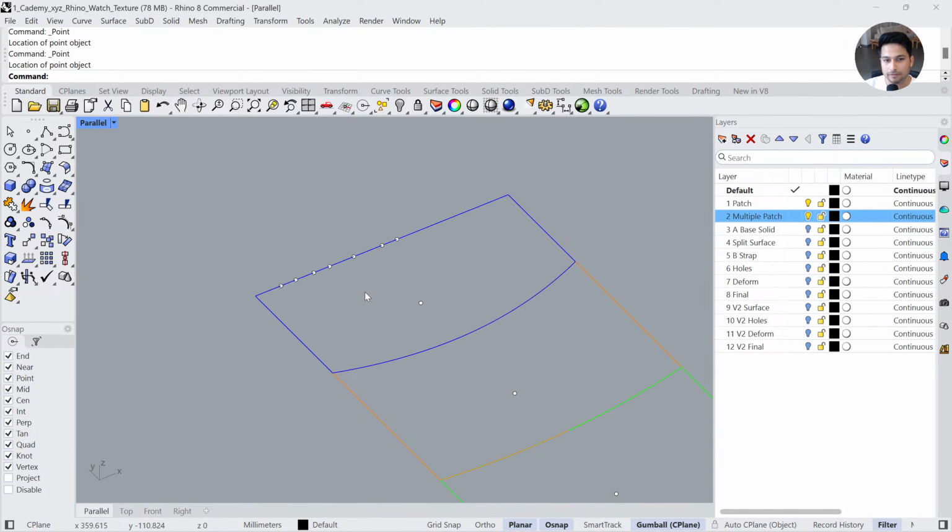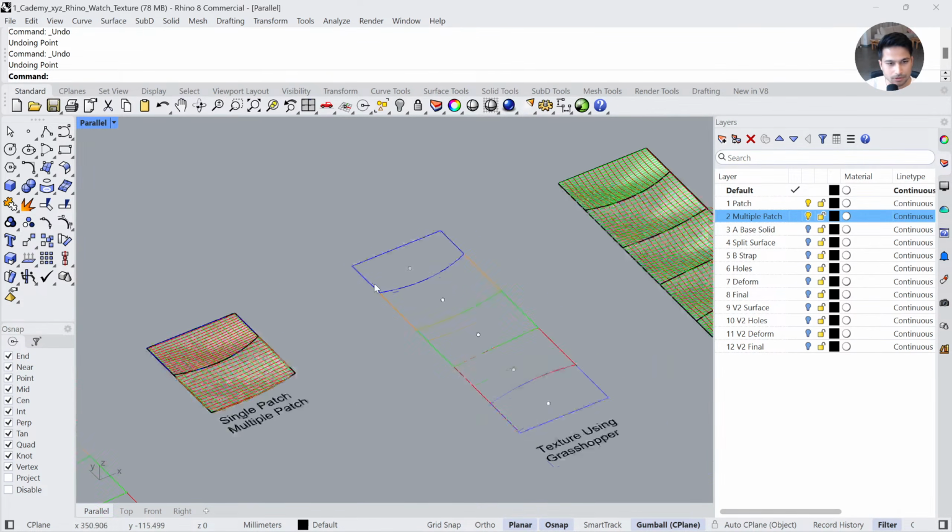But it will also give you more spans and more deformation on the surface. And if you use a bigger amount, you will get a smoother surface, but it might not adhere properly to the edges, okay? So 1 works fine in most cases, but you can also change that if you don't see the right result, okay?